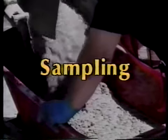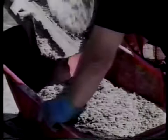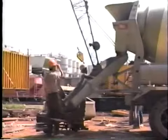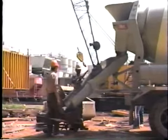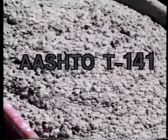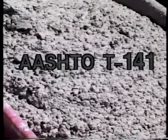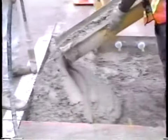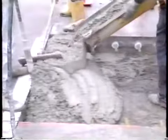Our first topic then is sampling. Before any of the tests can be performed, a sample of the concrete is needed, a representative sample. The concrete to be tested has to be typical of the entire truckload. Sampling should be done according to AASHTO designation T141. The basic rule is this: don't take the sample from the beginning or end of the discharge. Take it from the first 1/3 of the discharge, but never from the first 2 cubic feet.